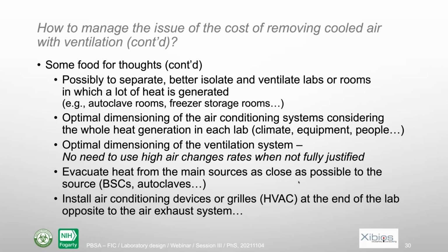So you could ventilate at a very low rate. And if your fan is well located, you won't need to change the air very often at a very high rate. So the location of the fan and the supply air is more important than the number of air change rates.